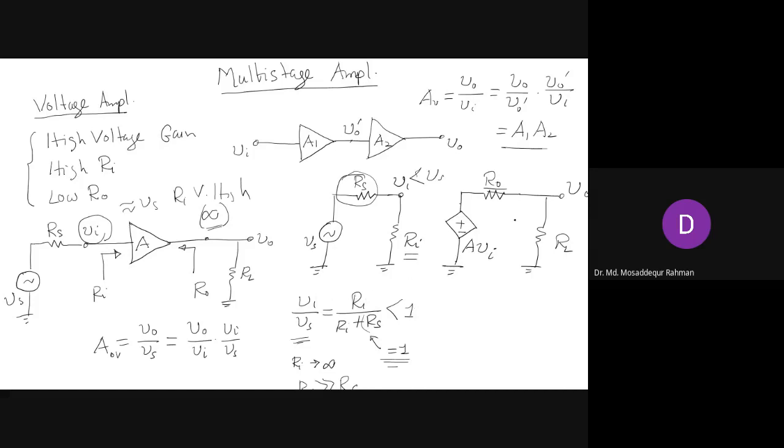At the output side, we have this equivalent circuit, and V0 is the output. The actual output of the amplifier is this voltage, and V0 will be part of this voltage. So not all of the voltage generated by the amplifier is transferred to the load.